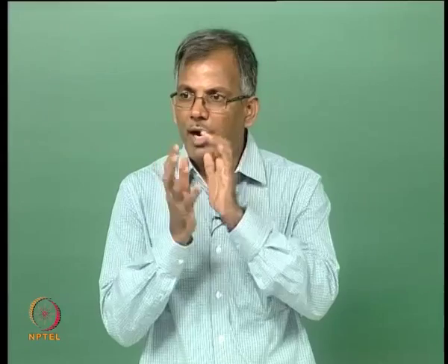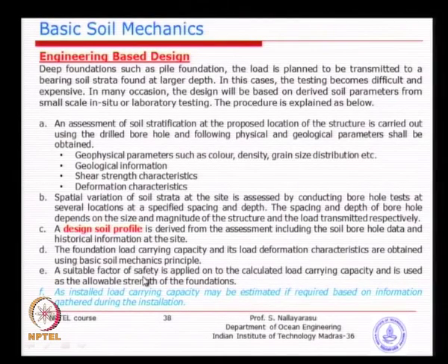We take only a fraction of yield strength as a strength of material used for design purposes. So, similarly here we need to apply a factor to the strength of the soil at failure, and that will be the strength used for the calculation of foundation depth. That is called a factor of safety.